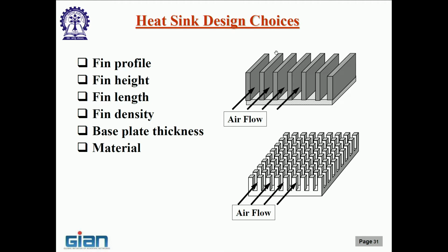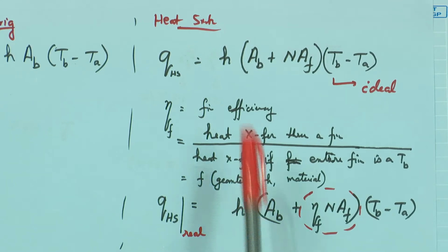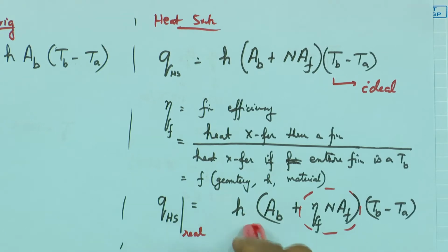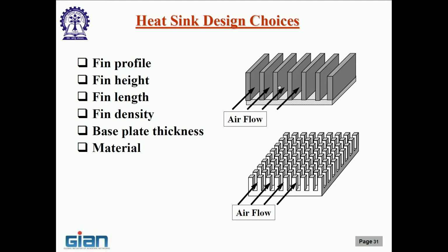Number of fins also important. Yeah, so if the number of fins are more, it will be better, right? Not always. I'll come to that. Yes, the thickness also matters, right? Area of the fin. That is correct, but the problem over here is, and we are going into the second level of details, if you look at the expression that I have written over here, I have taken this h to be the same over here and here. Actually the h is also a function of spacing between the fins, the channel width.